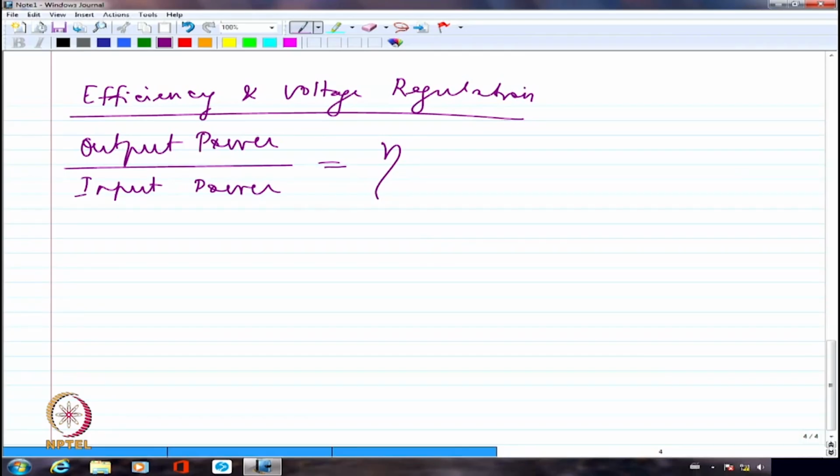For example, in your PC, you have that SMPS. That SMPS will always have a transformer inside. That transformer probably is going to carry only about 300 watts of power, nothing more than that. But out of 300 watts, maybe it will be dissipating 20-25 watts, and it is a pretty constrained space. There is hardly any space available. So you might have to make sure that adequate cooling is being done. If adequate circulation of air is not available, I might have to fit a small fan. That will consume more electricity, that is different, but I have to make sure that nothing fails, right?